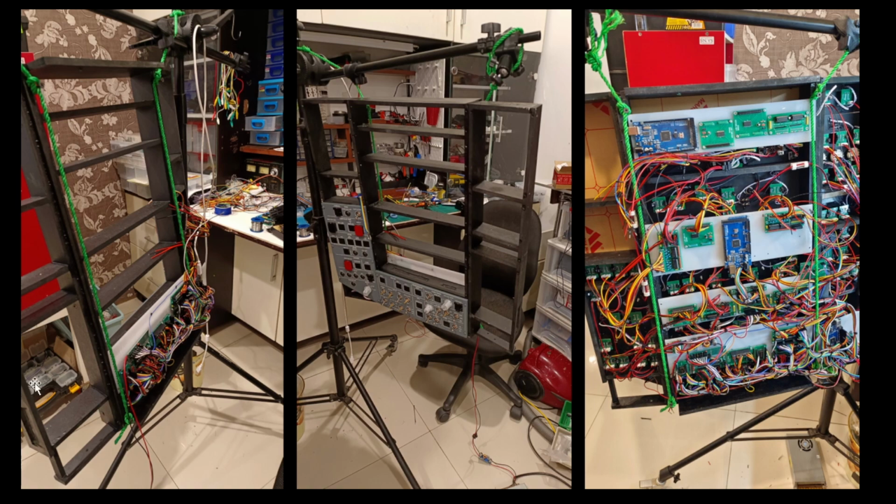This is a pre-made frame using MDF, pre-cut, and the size is just enough for the panel to sit on top of it. You install from one panel to the other and connect it to the circuit using a shift register or directly to the Arduino Mega 2560. Then for output, you have to drive via an LED driver. I'm using a ULN2003 driver. I'll show you the circuit later in the electronics part.